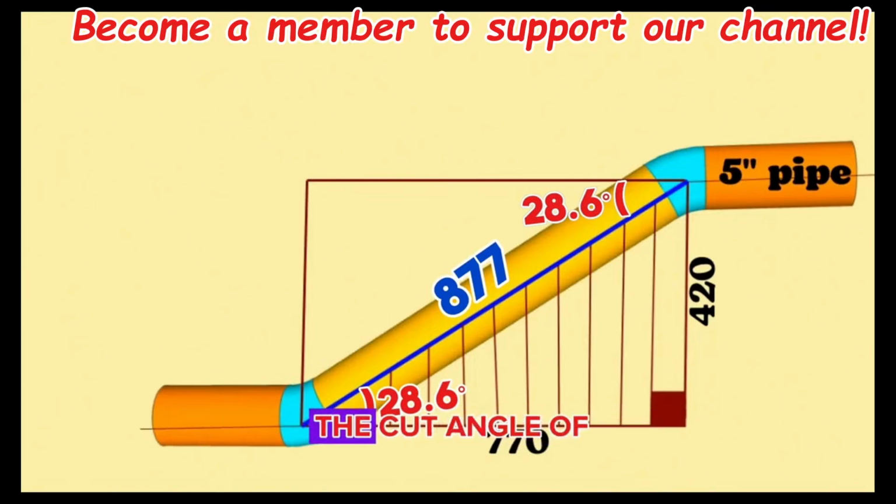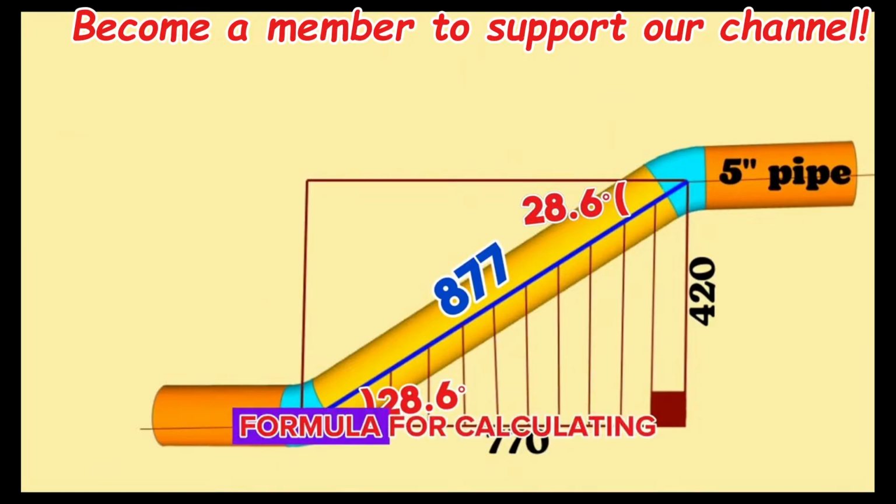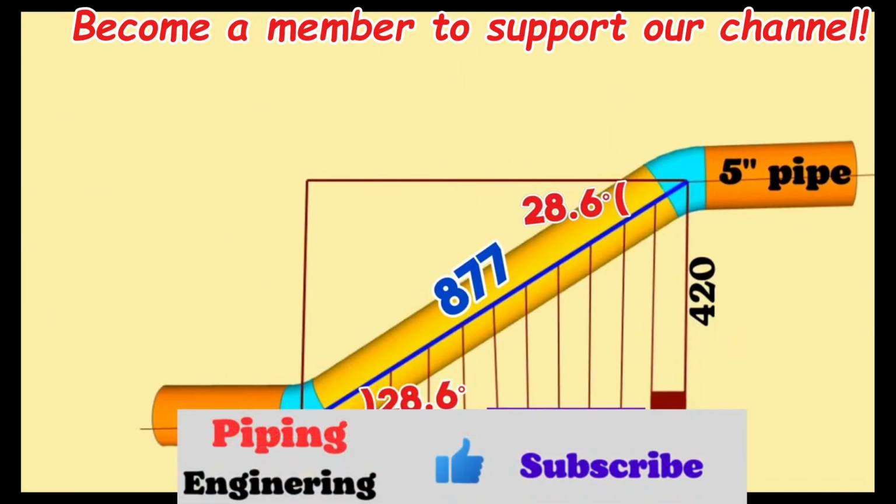28.6 degree is the cut angle of the top elbow in the same time. Now let's calculate the dimensions of these elbows from the center to the end. Formula for calculating center to end distance of such cut elbows is as follows.